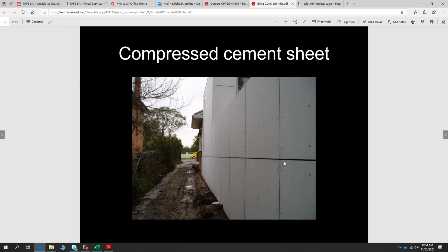With all the issues around aluminium sandwich panel cladding, so combustible claddings, fibre cement sheet cladding has taken off a little bit more, and you see that used a lot more commercially, but also in some of the express jointed systems like this in the higher end residential builds, but also for some of your cheaper builds, fibre cement sheet weatherboards, etc., get used as well.